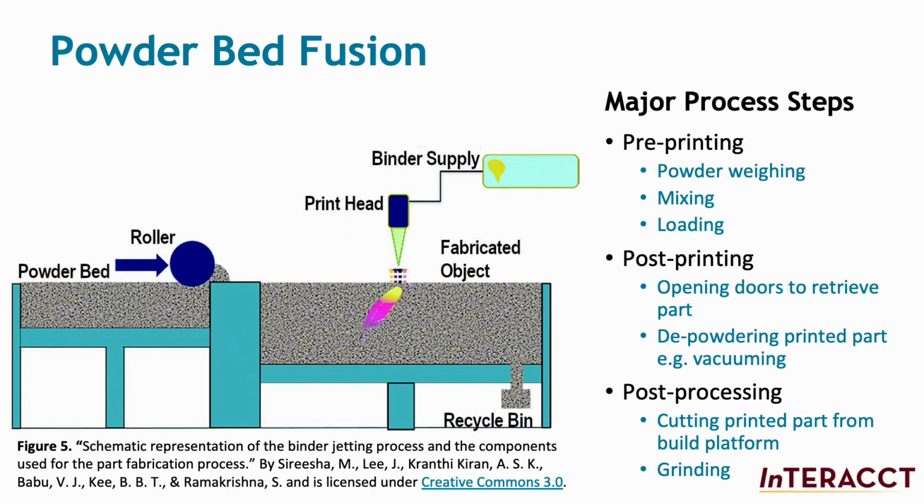This technology includes two main types of processes: selective laser melting and electron beam melting. For selective laser melting, a blade is used to spread a thin layer of powder across the platform that is then melted by reflecting a laser beam using a mirror. The process is repeated with a fresh layer of powder, building the part layer by layer. Electron beam melting is, as the name suggests, an application in which an electron beam is used to melt the powder. This causes less residual stress compared to selective laser melting, with less distortion, and as a result, the need for anchors and support structures is reduced.